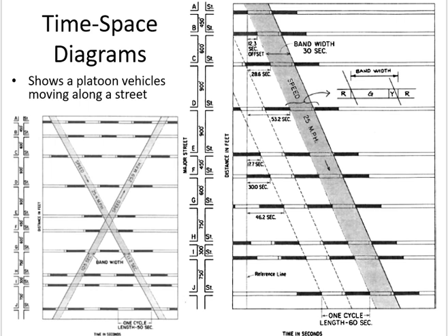So I use the same speed with this distance. Distance upon speed gives me now 28.6 seconds. So from the first green, I will go forward 28.6 seconds and make the next green, like make the green for the next intersection. Clear? Okay.